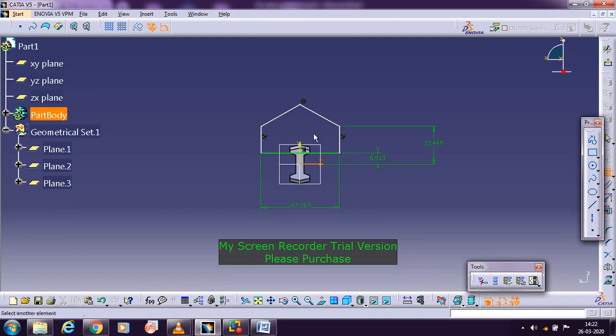Similarly, from the central axis to this apex point, the corner point which you can see, you need to show it here. Similarly we have shown the dimension here, since this is separate and this is separate, I need to show the dimension here. From the center line, always make sure that we are showing the dimension. All the dimensions should start with the central axis.